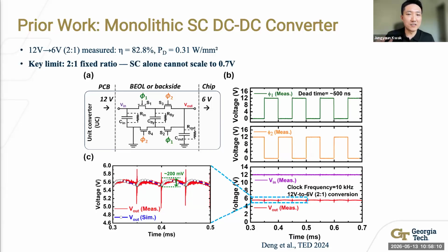But after that, while I was writing this TVLSI paper, I measured the reliability and temperature dependence, developed a compact model for that, and ran the aging simulation. Within the thermally constrained system, the first thing we can do is look at temperature. For silicon devices, the industry generally guarantees up to about 85 Celsius. So does this DC-DC converter work at 85 Celsius? At that time, the answer was no.